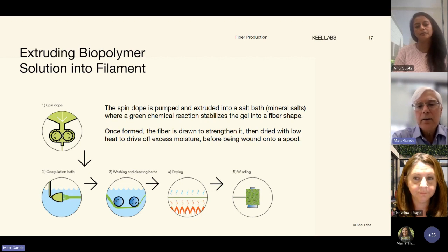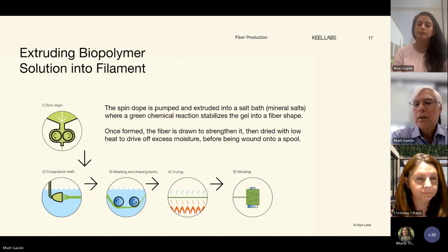So depending on the end use application, that filament tow that we made could actually go into a filament yarn. Our focus is more on being able to blend with other materials. So we want to make this into a staple fiber, so that filament yarn can easily be texturized through a number of different methods, such as a gear crimper or stuffer box or anything that will give some texture to it, so it'll spin well in the final process,